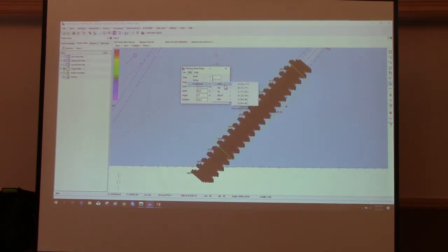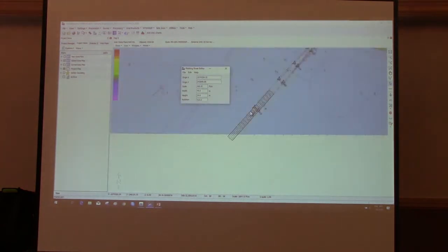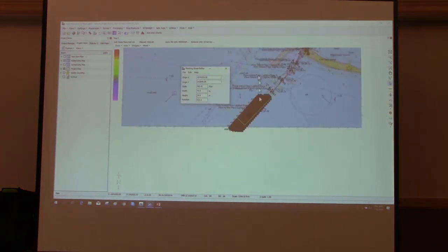So if I go to the ANSI E size sheet and click on it, it sets the proper length and width, and then I can just change the scale. If I go down to 50 or so, I'll drop it down. Once I do that, I save this as a plotting sheet. I won't save that one because I think I have one in here.